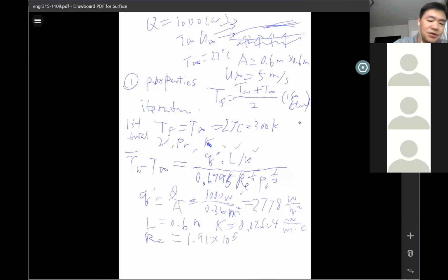Okay. So what else? Prandtl number. Prandtl number from the table is what? 0.708. Yeah, it's 0.71 basically, right? For air going through it. So I have everything. So my average T wall calculated from here is 267. Is that 267? Yes, 267 K.